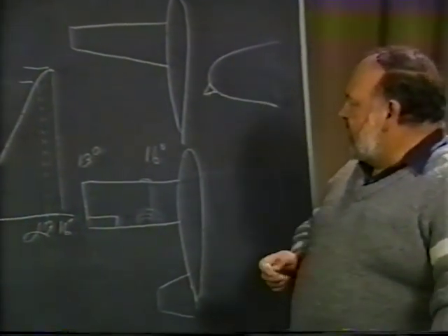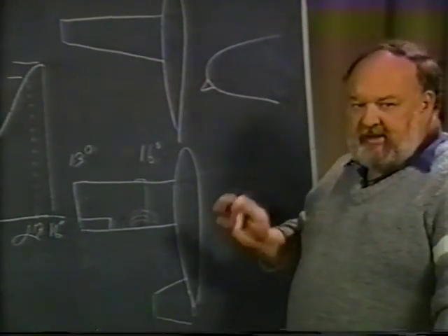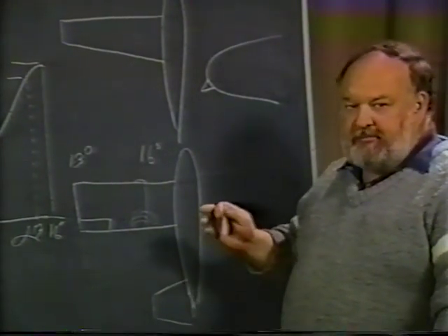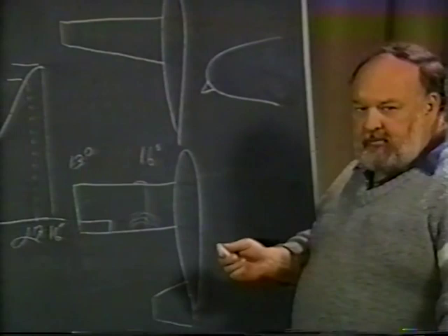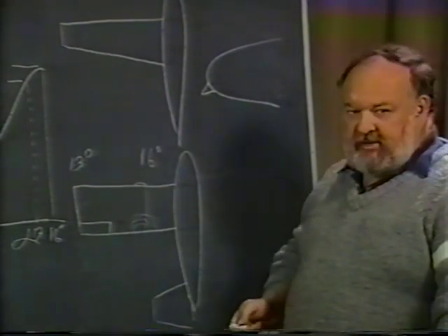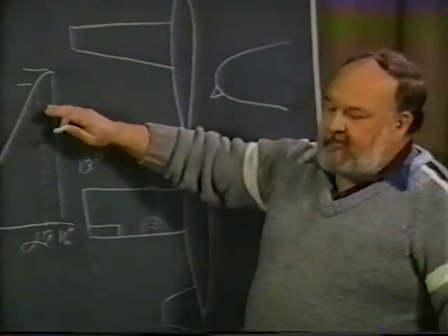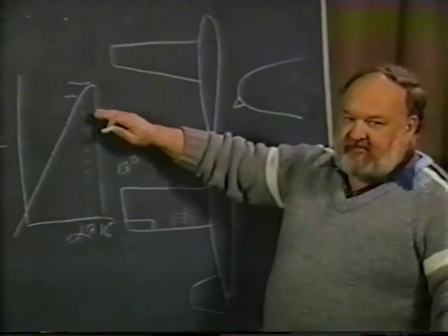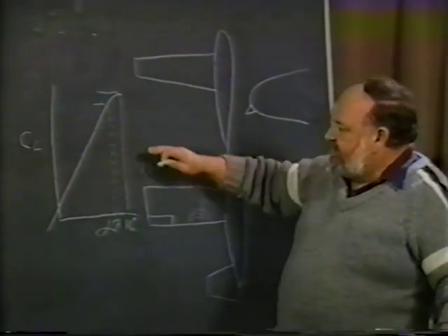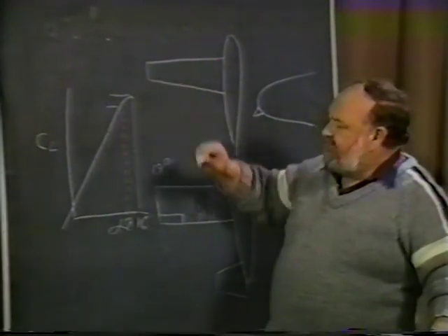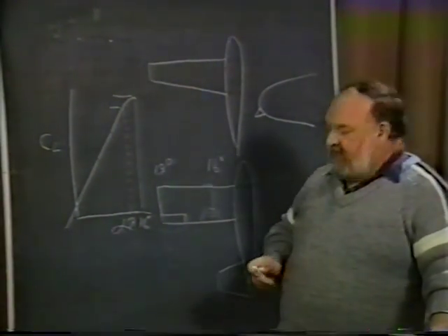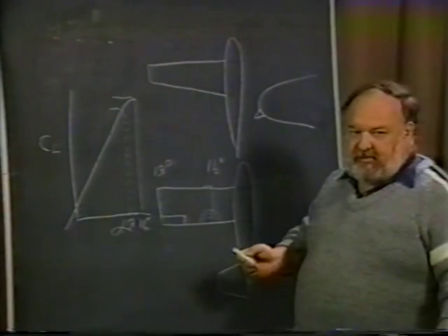And all this is really doing is forcing the leading edge to stall, or to at least build up a turbulence to the point where it forces that section of the wing to stall. But there again, what you've done is reduced the maximum lift capabilities of that airfoil section within that region. So definitely, if this part could have gotten to 1.6 to begin with, it definitely cannot get that high once you put the stall strip on it.